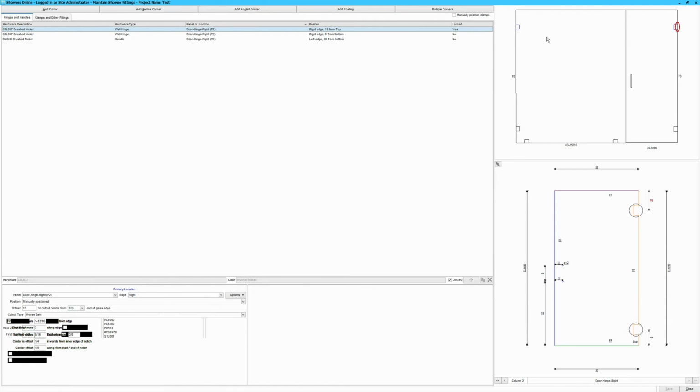So now these things have both turned blue, so that tells someone who may be checking the glass sizes something's been moved here. Now, that comes in handy when you've got numerous panels with clamps top and bottom, and they're being moved all over the place, and you're not quite sure which ones you've moved and which ones you haven't moved. You can keep track of that by seeing which ones are blue. That's kind of a helpful hint.